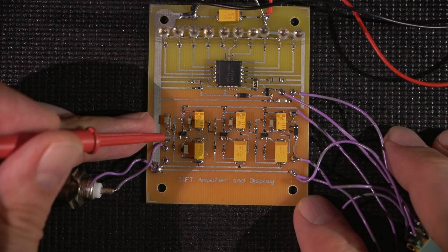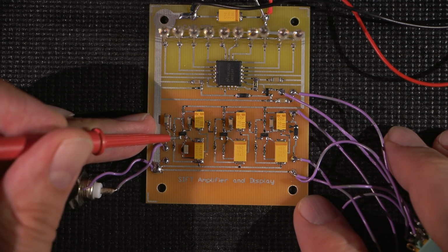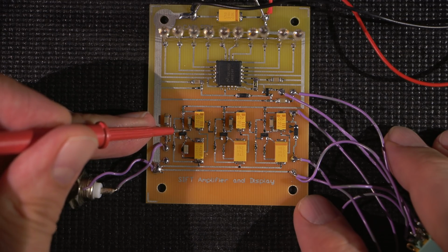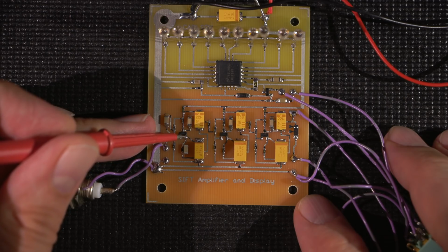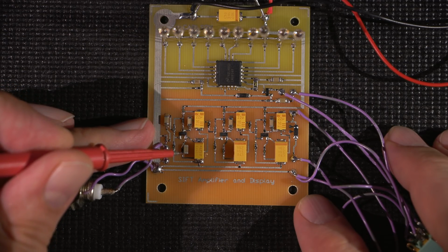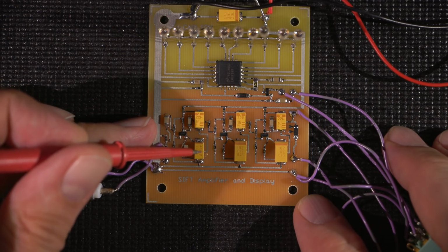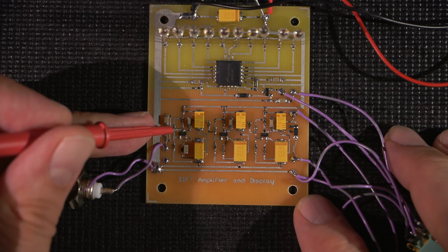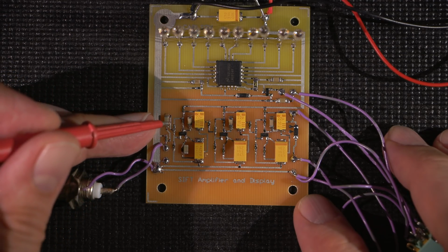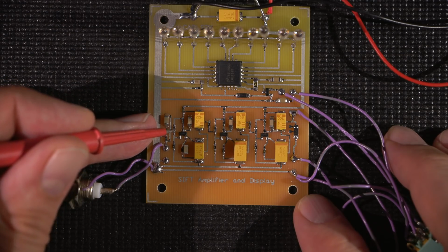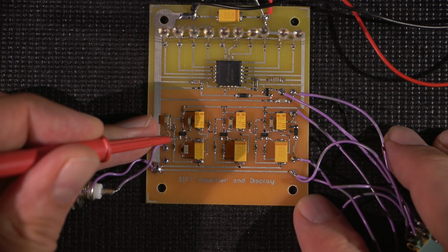Since we know that we have a signal running into the base of this transistor, we're going to have an amplified signal on the collector, because we can see here that we have a single resistor on the emitter to ground, and we have a capacitor running to ground. So obviously the signal path is going to be running out here, right? So what we're going to do is probe this point here with the scope.